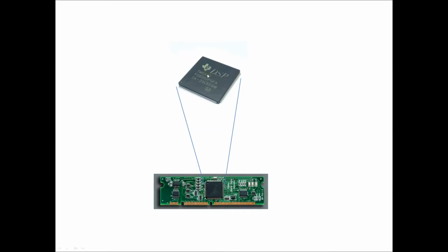The criteria for selecting this DSP is firstly fast floating point computation, and secondly ADC for high frequency sampling. Port 60 and 61 of the GPIO on the development board are used for gate pulse output. One of the ADC channels is used for sensing load current, which comes from the signal conditioning board. The DSP is programmed in Flash for standalone applications. Now let us have a look at the algorithm.